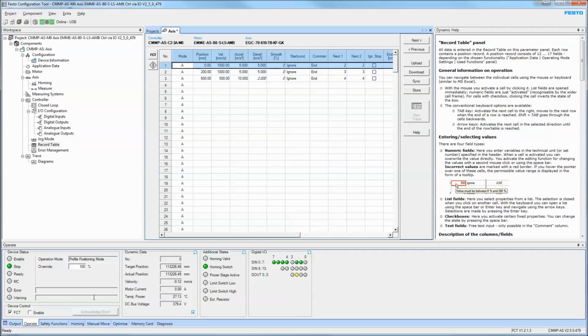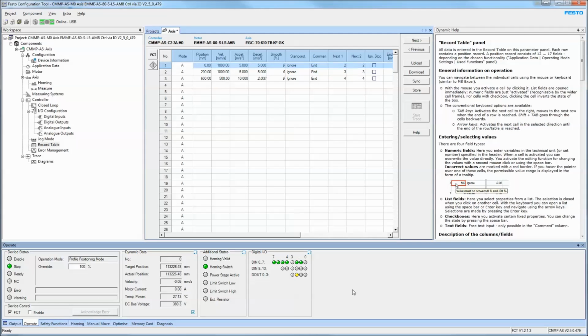All right, so at this point in time, let's look at our hardware. With the controller right now, on the top, you've got an X1 25-pin connector, and you've got a power connector on the X9 at the very back top. You need to have that hooked up to the 120 or the 240. You need to also have that X9 connector hooked up to 24 volts. The X1 cable needs to be hooked up to your I/O.